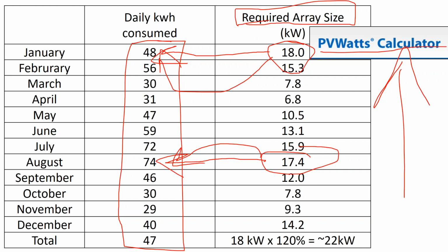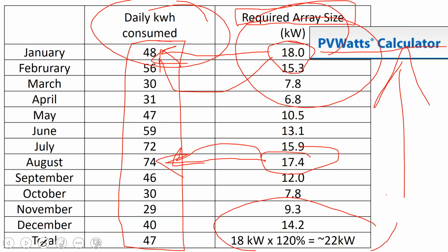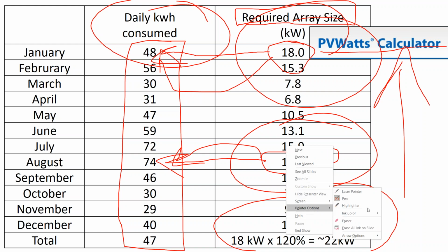But what I have not taken into account is that I'm using an average consumption and an average production, but that's actually going to vary by overcast days. And so I'm probably going to want to oversize my off-grid array above and beyond 18 kilowatts so that I never run out of electricity. And generally, if you're doing a 10 kilowatt or 12 kilowatt, you might as well go up to 18 kilowatt. By the time you get through this detailed design process, the cost of the module is not the primary driver of the system. Then again, there are some other things to point out.